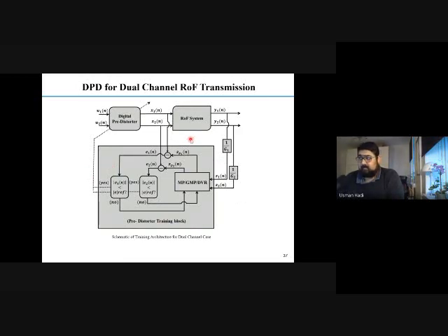After the gain adjustment, because there are amplifiers here, EDFAs, optical amplifiers, we try to adjust the gain and bring it back to the normal level by using the adjustment gains here. And then we bring Z1 and Z2, which are actually Y1 and Y2 with the gain adjustment, to our system that we call the training block or the pre-distorted block.